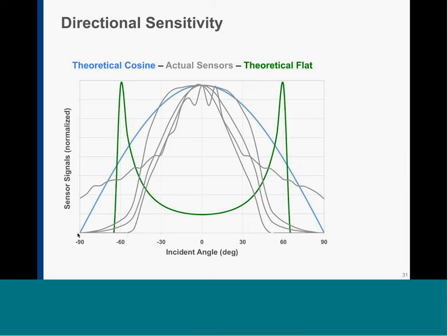It's interesting because we thought, how can we have a sensor whose signal does not change if I have a surface moving under it horizontally, like a person with a white shirt moving around and not really affecting the signal? And we came up, if you compute the inverse square law and the cosine law, with that theoretically flat, where it's much less sensitive under the sensor. Sensitivity increases as you go to oblique, but drops dramatically if you want to have a confined field of view, which, as we will see, can be pretty critically important.